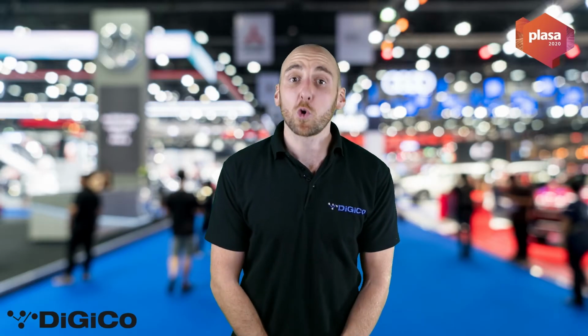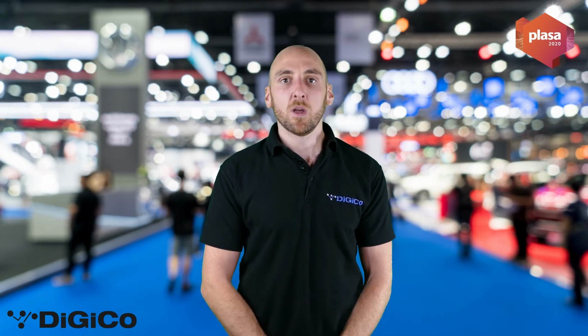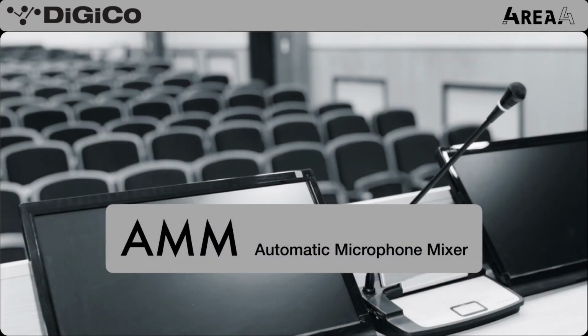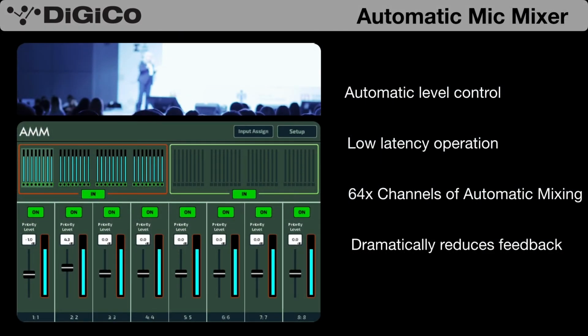Let's now examine a corporate venue. Let's say a conference centre where we have a debate. The Fourier 4 has an inbuilt automatic microphone mixer, or AMM for short. The AMM is perfect for debates or conferences where there are multiple mics open at once. Without the AMM, you'd need an engineer fading up each speaker's level as they begin to talk, or you'd experience high levels of noise and be at risk of feedback.